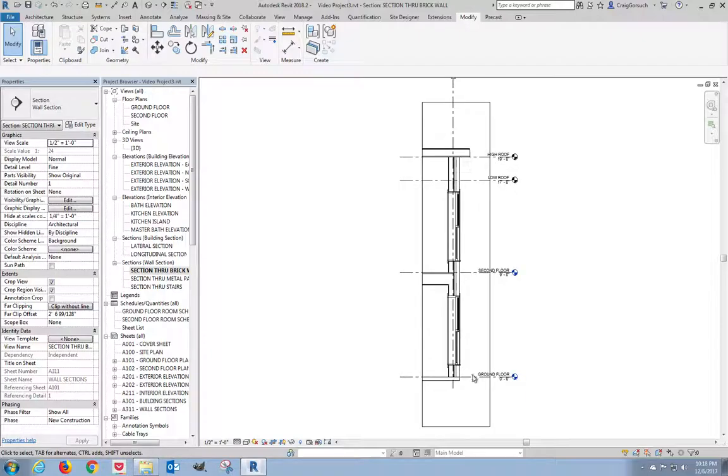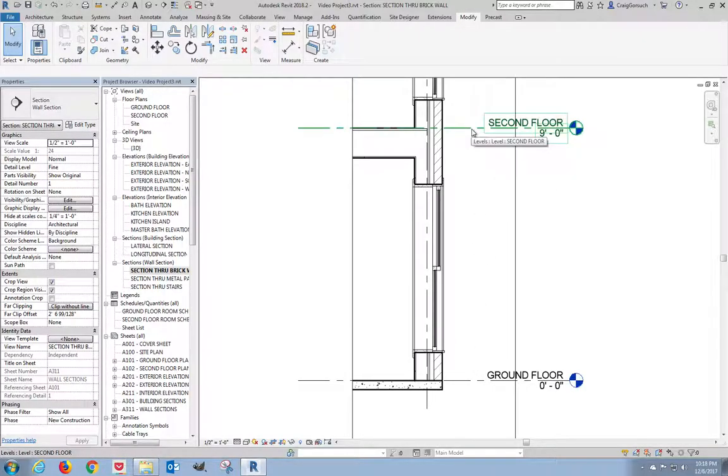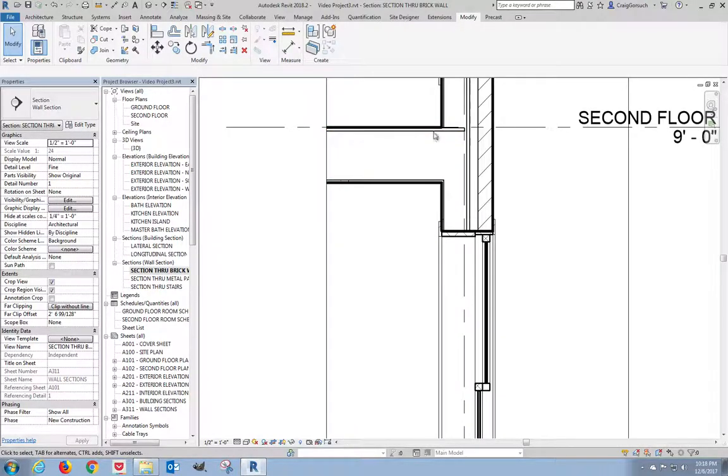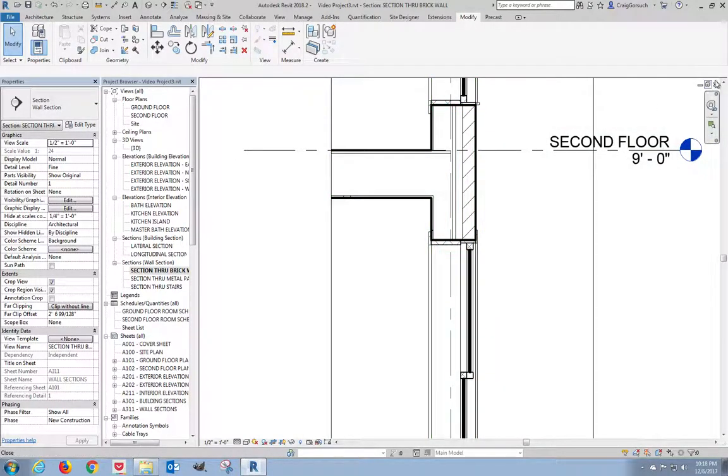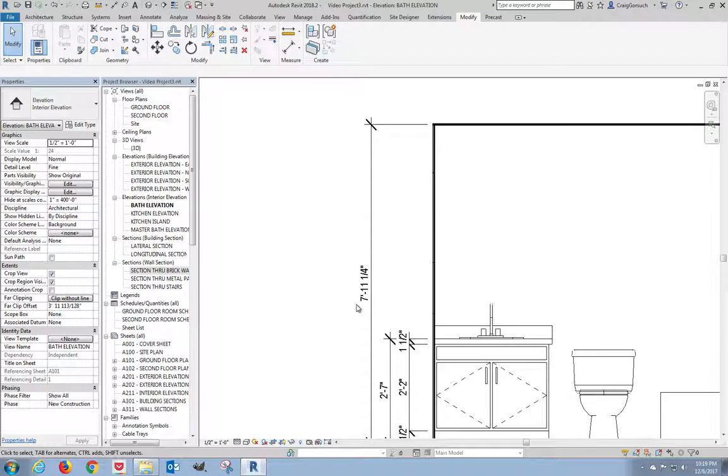The reason we have such a strange dimension is because we have a nice, pretty, perfect dimension for our second floor. When you do the math for 3/4 inch plywood, and then 11 1/4 inches for the joists that are holding up the plywood, and then you have another 5/8 of an inch or 1/2 of an inch for gyp, it's going to give you an odd dimension. So that's the only reason this dimension is not the perfect, nice, even 8 feet.